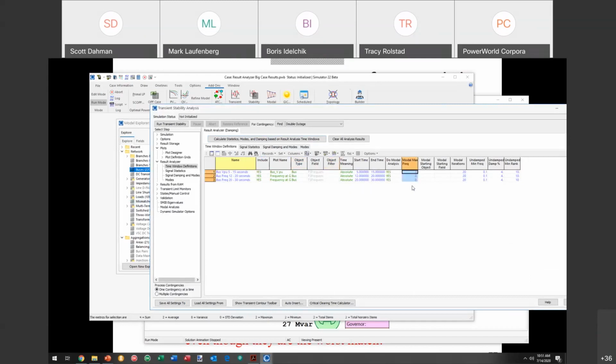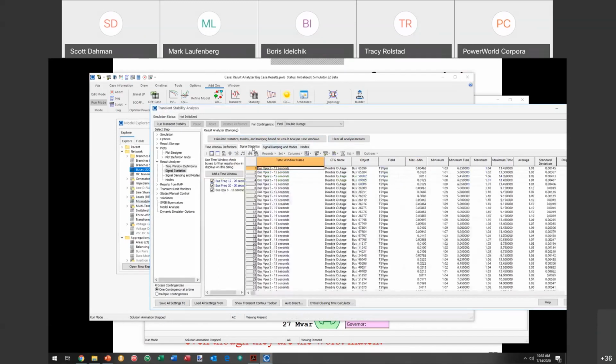If I had put this max frequency in there at 20 hertz, it would have taken several minutes. So you double that value and it gets 8 times slower. So be careful with the settings that you're looking at.